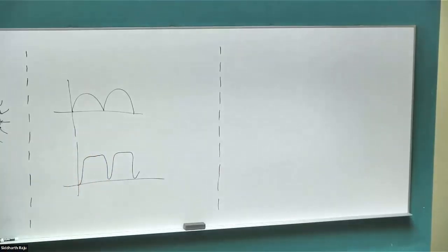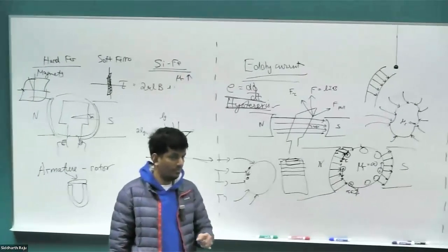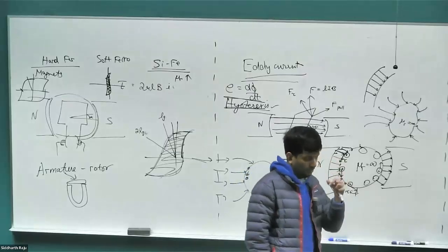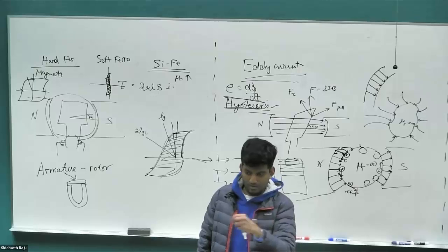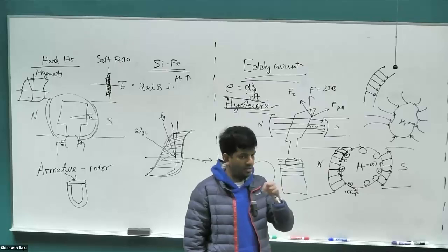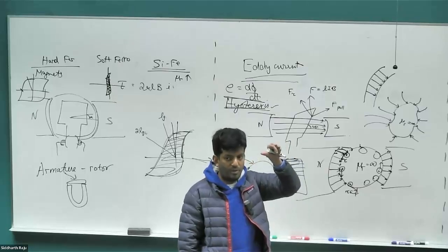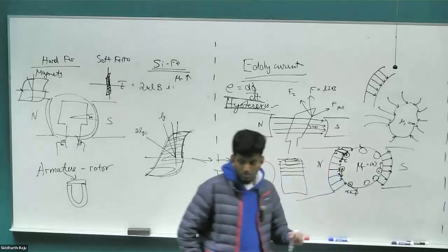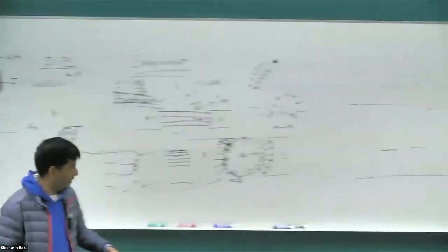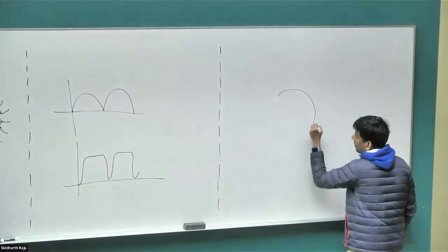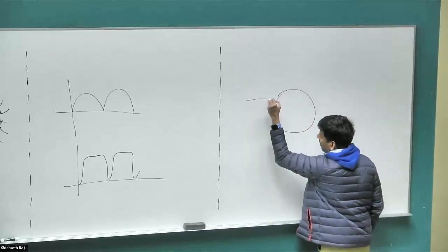Thomas, you already gave me the answer in a different question. In between the north and the south. When we looked at our rotor structure, the stator structure that I passed around last class, we saw that the magnet did not enclose the full 180 degrees. There was a small portion on the top where the magnet wasn't covering, and a small portion on the bottom. So in those regions, the B field is going to be very, very small. There is a very important reason why we don't do full coverage: to reduce the armature reaction, which we will look at after spring break.